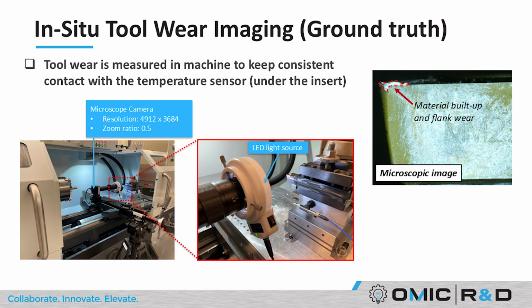In this case, we take a picture of the tool and focus on the tool tip and cutting edge, and measure the width of the tool wear with this microscope based on the images.